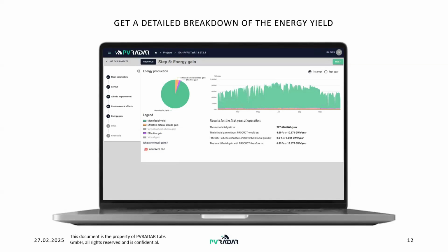So we see that we are able to calculate the theoretical monofacial yield of the power plant. After that, we identify that the bifacial gain without the product, that means associated to the natural albedo conditions, is equal to 4.769. And on top of that, we have the benefit from the high albedo material, adding an extra 2.2%, resulting in a 6.9% of bifacial gain for this project.